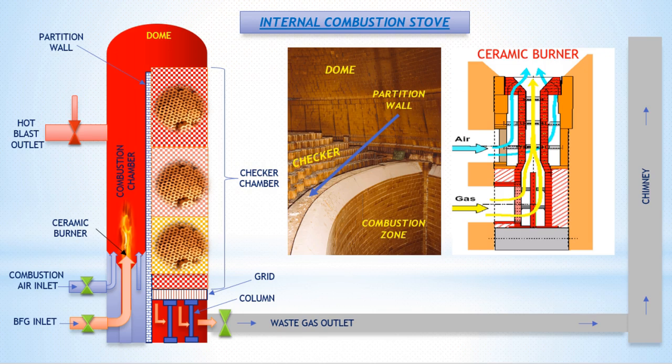Chimney is a critical component of internal combustion blast furnace stoves, responsible for safely venting flue gases and maintaining a stable combustion process. The chimney vents flue gases from the combustion chamber and regenerator to the atmosphere. The chimney helps maintain a consistent draft, ensuring stable combustion and efficient heat transfer. The chimney is a vertical steel structure outside and inside, typically made from refractory materials like fire brick, ceramic.